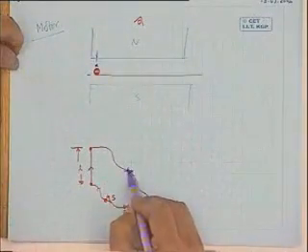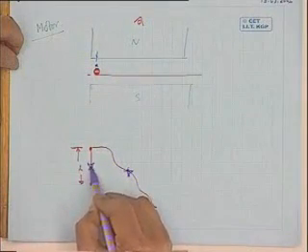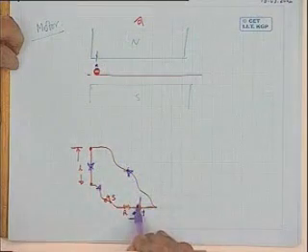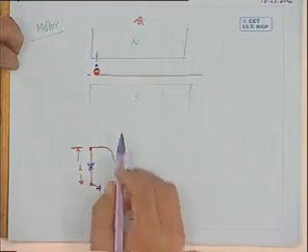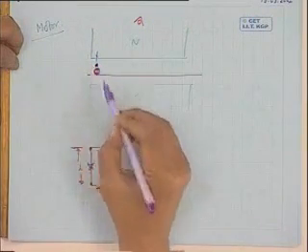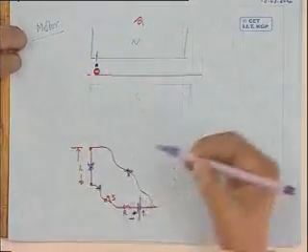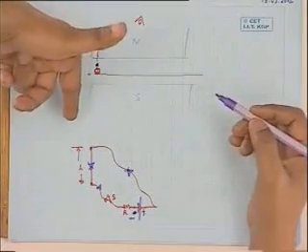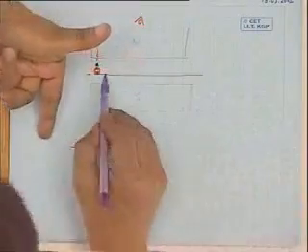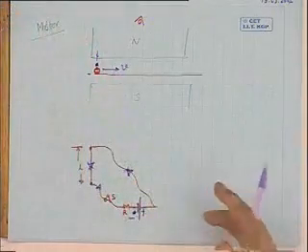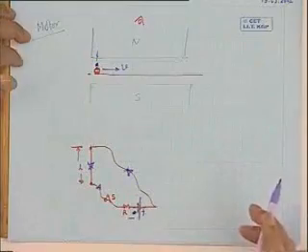Suppose there is no track on this side. So the current flows this way, I, like this. This is the plus of the battery, minus. So if you close like this, in this case it will be a dot, current coming out from the paper. And if you now apply the left hand rule, this will be B, this will be I, and the conductor will start moving in this direction with some velocity.